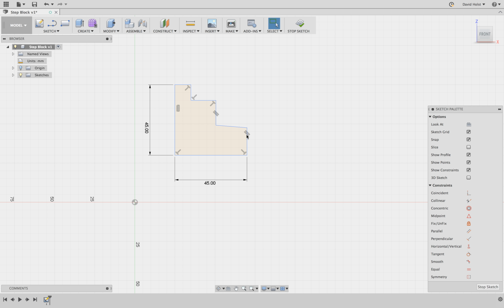You can see this one here, I've actually drawn them a little bit wonky. And what I want is I want them to be 90 degrees to each other, or perpendicular. So I can actually click on this perpendicular constraint here. And I can click on this line and that line. And see, it's actually made them perpendicular to how I want, which is fantastic. So I just hit escape again.